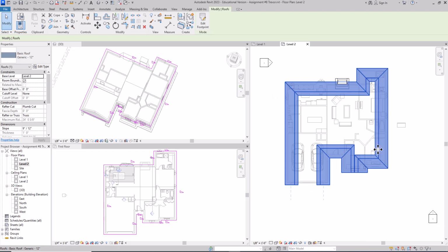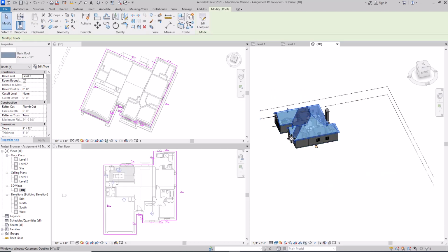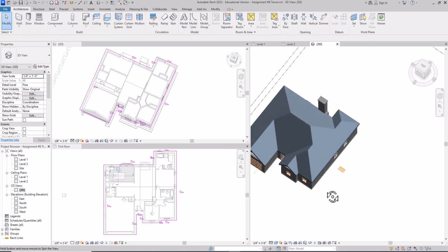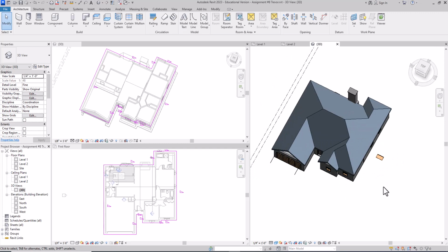All right, I'm going to pick the green check mark and I want to attach the walls to the roof. So now I can go over to the 3D view, check it out. In this one, it looks pretty good here, and you'll be able to create your roof. All right, do the best you can. If you create just a little slab or leave that one, it's okay.